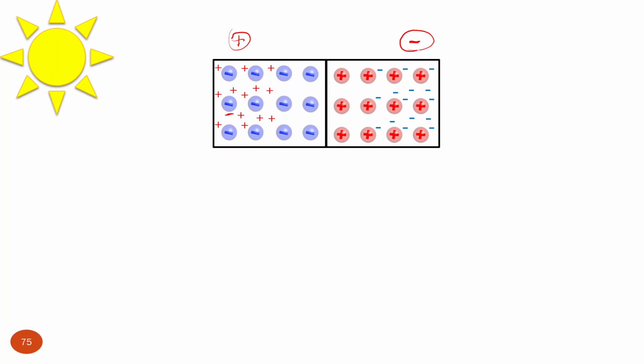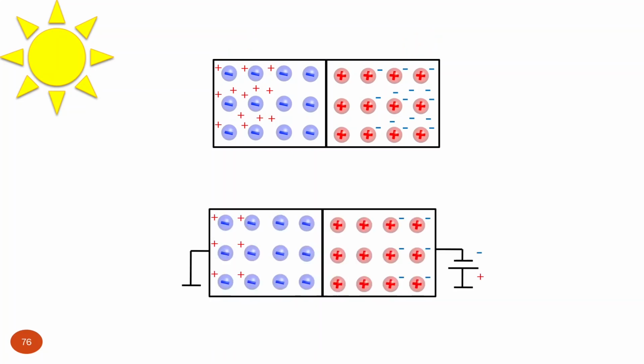We apply external bias, and applying external bias is actually applying some negative potential. Let's say what we had before: here we have excessive negative charge, here is positive. It could be modeled as, we don't shine light, so we have some shutter here, so it remains in the dark, but we apply negative potential to the n-type region and positive potential to the p-type region, external bias.